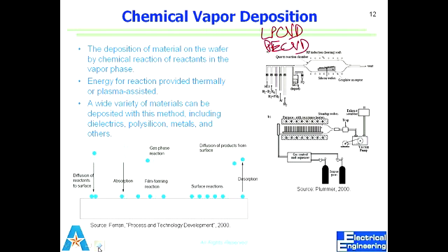We have so many electrical engineers. What do we need to do when we do RF energy transfer from one medium to another medium? Match the impedance. Match the impedance, right? So with RF power, the first thing is we have to match the impedance, right? We do that for our stereos, speakers, right? They have impedance, and then what happens if impedance does not match? Maximum power is not transferred. Refraction or reflection? Reflection.